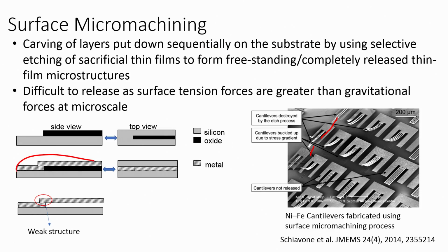You see here, we have silicon dioxide on silicon, we deposited a metal, and then we have etched the silicon dioxide. So, silicon dioxide here would be a sacrificial layer, it will sacrifice itself. When I sacrifice the silicon dioxide by etching it in buffered hydrofluoric acid, what will I have? I will have a cantilever made up of a metal.